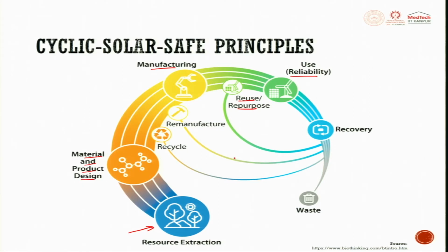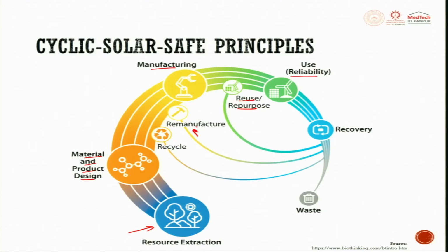Now, remanufacture some of the components, for example, in additive manufacturing, if it has an assembly of 2 or 3 components and one component goes wrong, that could be put in as a module there. So modular design, in the topology optimization, the modular design is also there. So remanufacture, right. Recycle is always the third option, when we try to completely melt the component and try to recover the material. So parts recovery happens here. I would put it here.